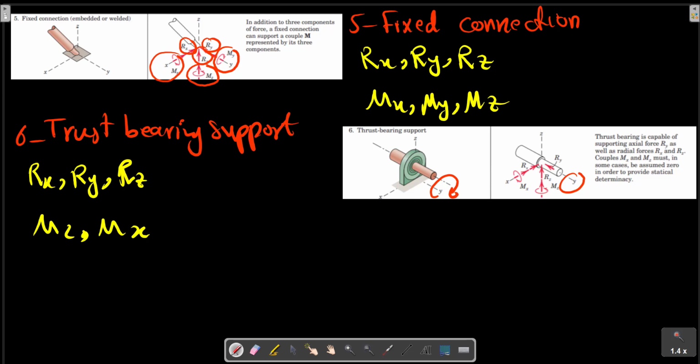In these examples, the correct sense of all forces Rx and Ry may be known or perceived to be the sense opposite to those of the assigned coordinate axes. Similar combinations can be chosen for the other examples. The sign of each force can be chosen arbitrarily, and after calculation we can realize whether our assumption is true or not.